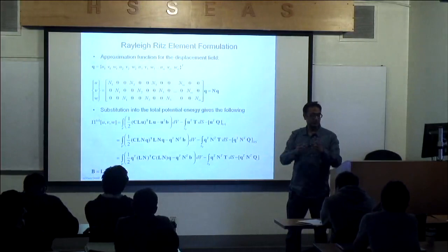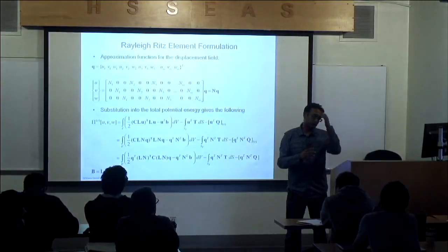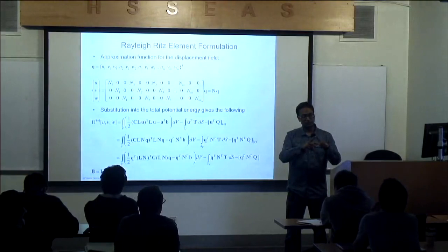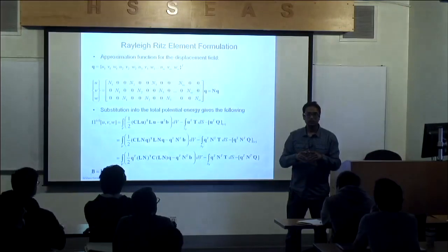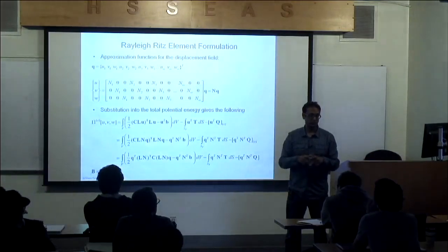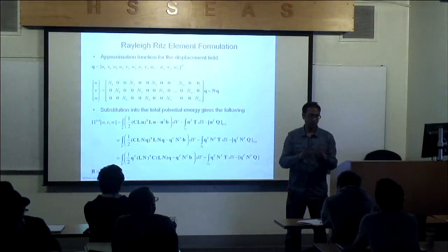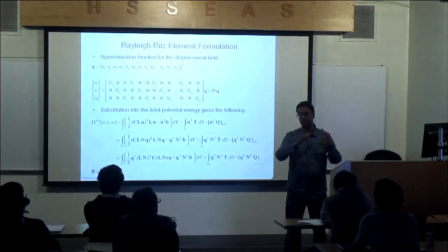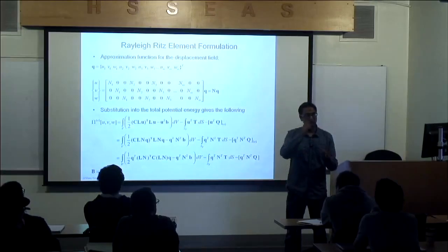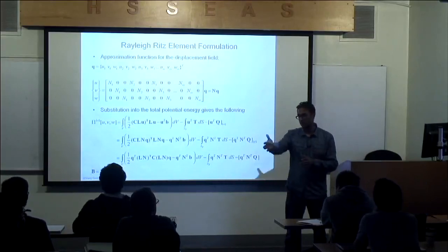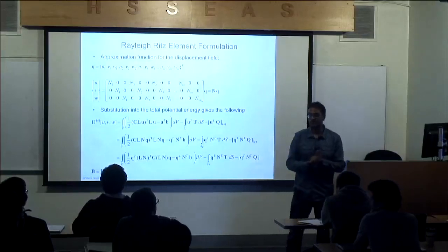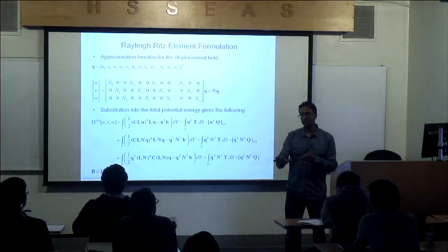Right? So let's take the example of a tetrahedron. How many nodes do you have for a tetrahedron? You have 4 nodes, right? In 3D. I'll show you a picture later. So how many degrees of freedom do you have? 12. So one element has 12, and your stiffness matrix has to be 12 by 12. We're not giving you that in the file, because you'll spend more time writing these matrices than doing the work, as you're experiencing right now for the heat transfer problem. Sorry, you have to go through the pain once. You don't have to do it again. Okay?